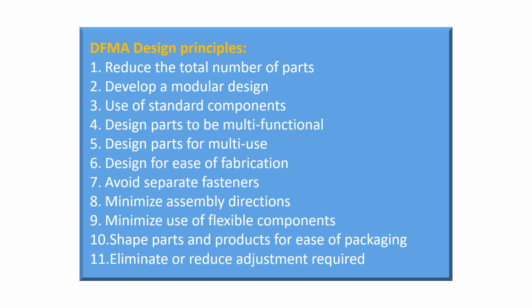6. Design part tolerances to suit manufacturing techniques. Tolerances tighter than the process capability should be avoided, otherwise further processing or sorting will be required. Use bilateral tolerances, and avoid unilateral tolerances.